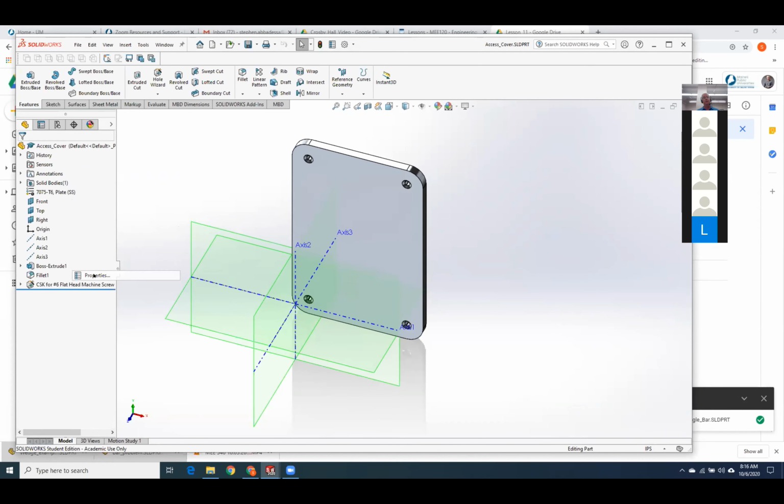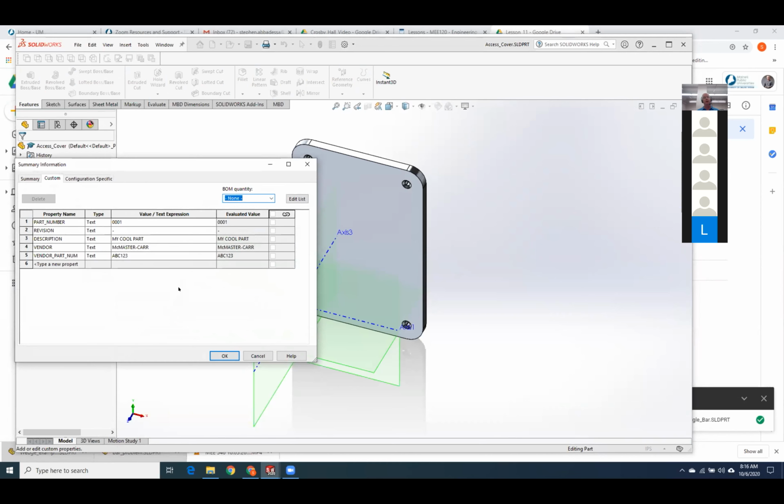We'll go to File, Properties, so that we go back to the attributes. We give it the part number that we want, so I pick something. 9876 is fine. We'll say we're going to use the dash for the initial release, no revision.